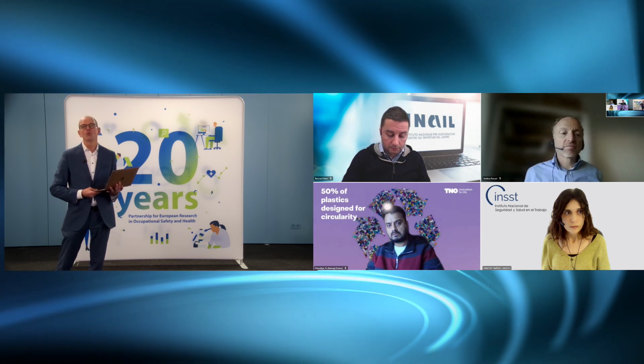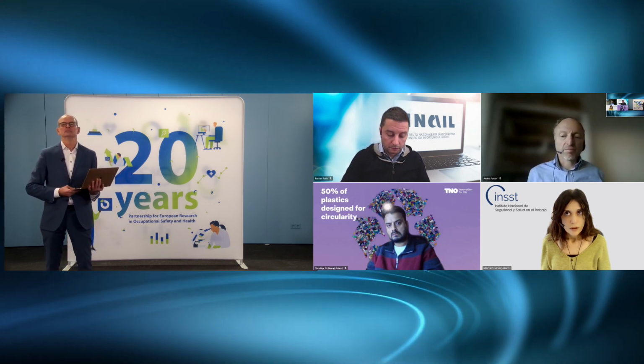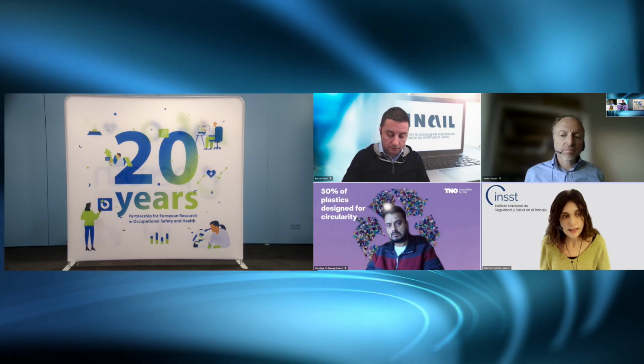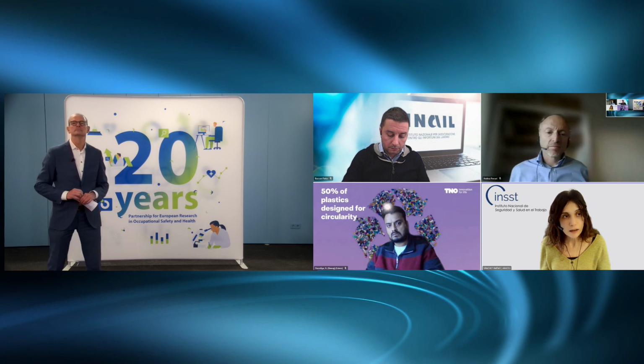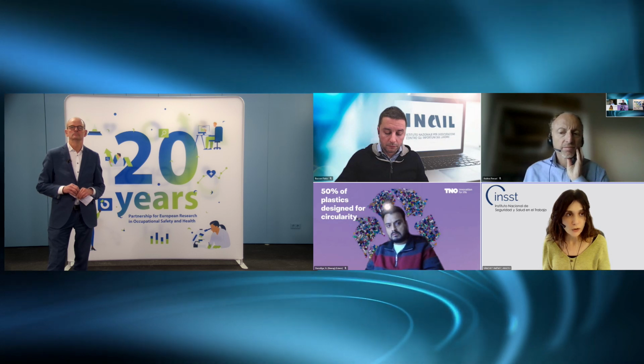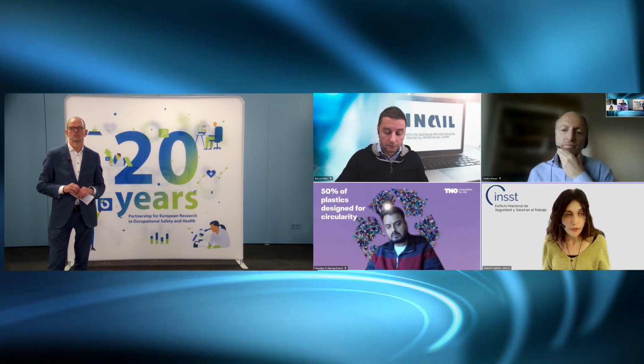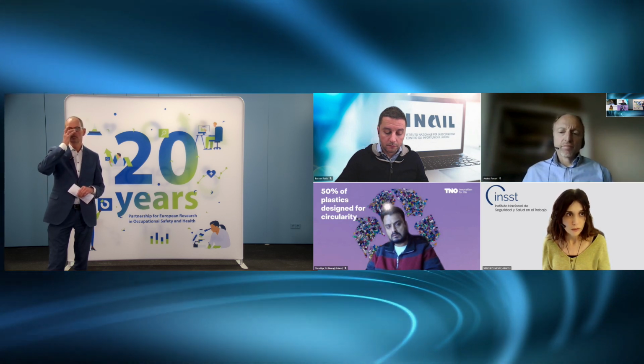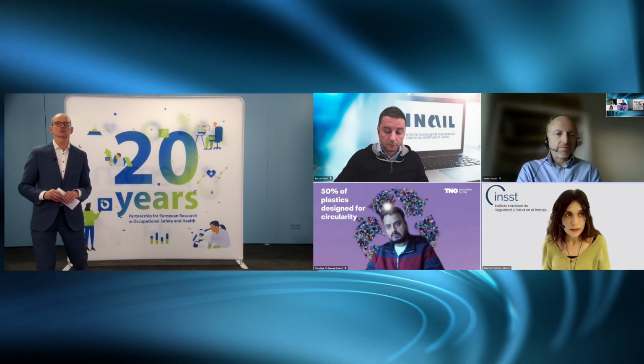Okay, thank you. And then the last question about measuring exposures. Araceli, I think this is also a question to you. Is there any guidance on when to do environmental monitoring and when personal exposure monitoring will be more suitable? Well, what the standard says, based on a tiered approach, is that if you have an indication of exposure, you do a basic assessment just to see whether there is a release to the workplace, which is what they call environmental monitoring. We used to call it area monitoring. You don't measure on the worker. Correct. And then if you see that there is an indication of release of the nanomaterial in the workplace, then you take personal measurements to assess exposure. Yeah, then you dig a bit deeper. What does this mean for personal exposure? Yes. Makes sense.